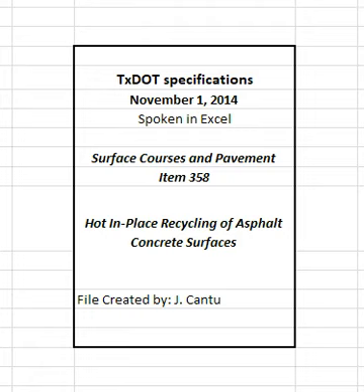5.3 Production testing. The engineer will test at the frequency listed in Table 2. The engineer may suspend production if production tests do not meet specifications or are not within operational tolerances listed in Table 2. The engineer may suspend operations if the contractor's corrective actions do not produce acceptable results. The engineer will allow production to resume when the proposed corrective action is likely to yield acceptable results.